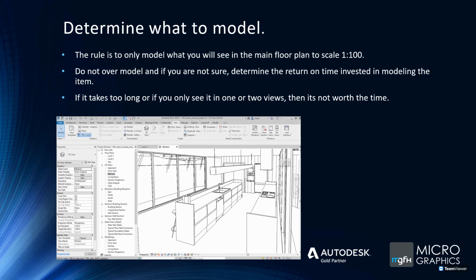Now there are various different ideas, but what I find works in the industry is when you model your main drawing, model as quick and with the least detail as you can. Because changes happen, and here is where you can manipulate the changes very easily. If you over model, that constrains the change management system.